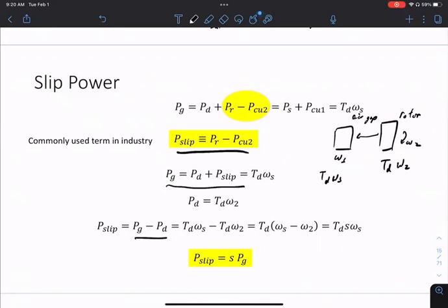Okay, so the torque times frequency, this torque times synchronous frequency. So where did the power go? Okay, so there's some power loss. And this thing is called Tslip. So think of this as the power that gets lost when it goes through the air gap. The power gets lost because you have a slip. And some power went away.